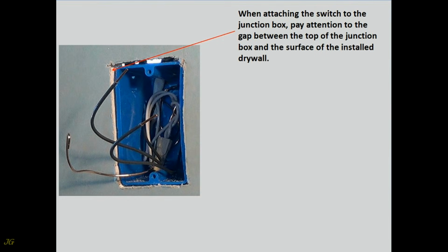When attaching the switch to the junction box, pay attention to the gap between the top of the junction box and the surface of the installed drywall. Same rules and restrictions apply as for a receptacle.